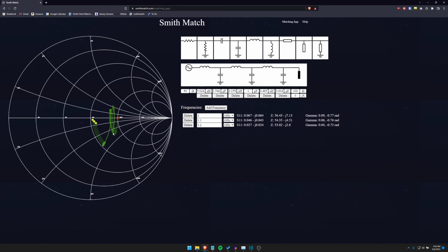but through the interactive Smith chart and some trial and error, it is not difficult to see how adjusting each component in the design causes the network impedance to either spread apart or cluster together, creating a broadband match at 50 ohms.